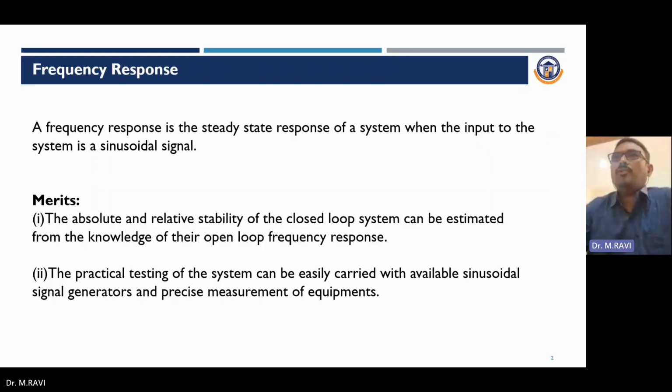Frequency response. Frequency response is the steady state response of the system when the input to the system is a sinusoidal signal. We already saw the time response analysis, which has a steady state and a transient response. Here, the frequency response analysis is the steady state response of the system to a sinusoidal input signal.